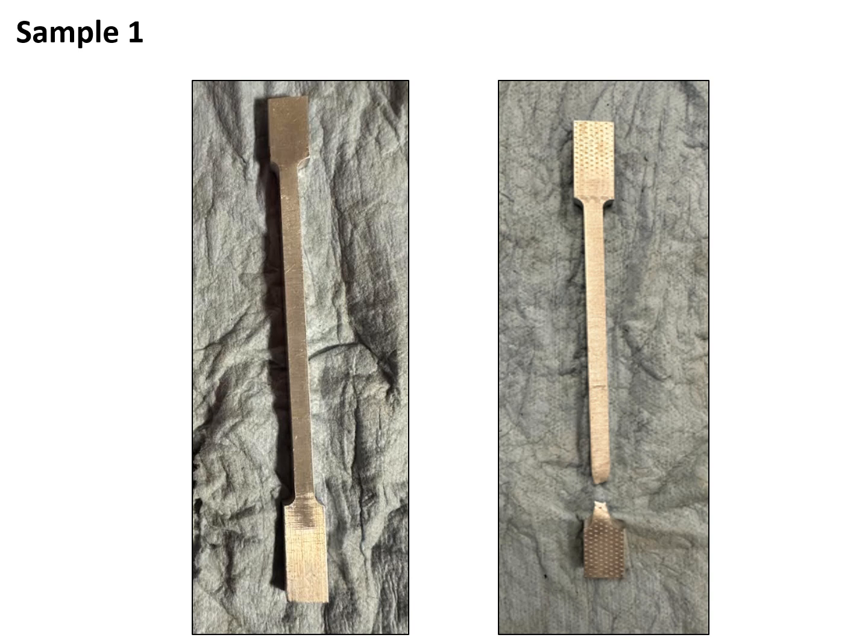For sample 1, the cross-sectional area was 0.0625 square inches, and when doing the tensile test for this material, it broke very close to the grip, and this was most likely because of a small imperfection at that point.